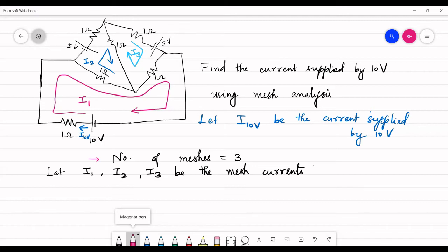So normally, remember this convention alone. Whenever a current enters an element, that end is assigned a positive sign and the end where current leaves is assigned a negative sign. So here the current enters positive, here current leaves it's negative. Again here, current enters positive, current leaves negative. So we are supposed to assign polarity for all passive elements. Voltage source is an active element and hence you don't assign polarity for that.